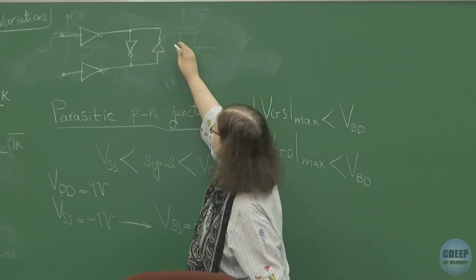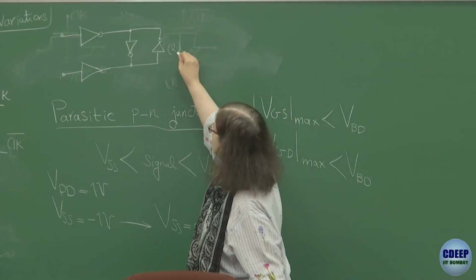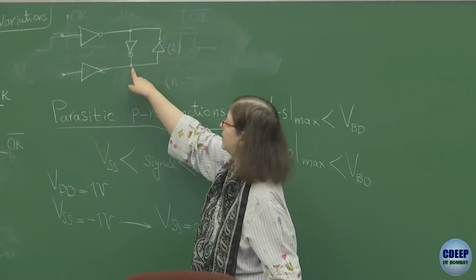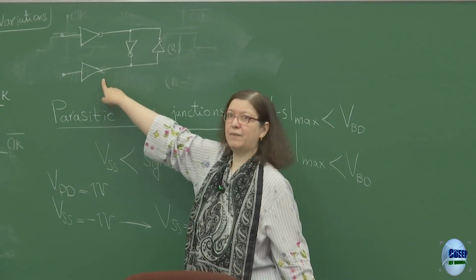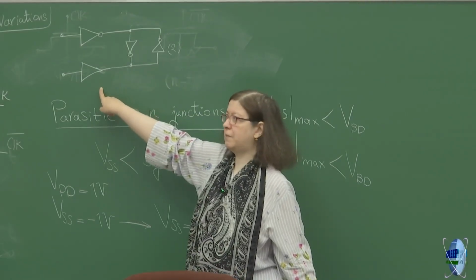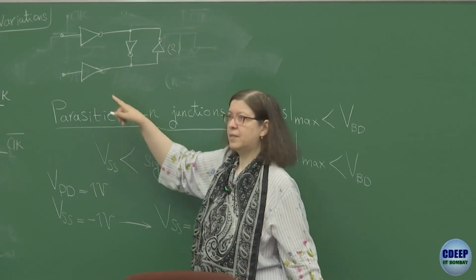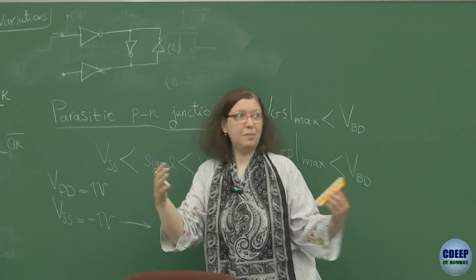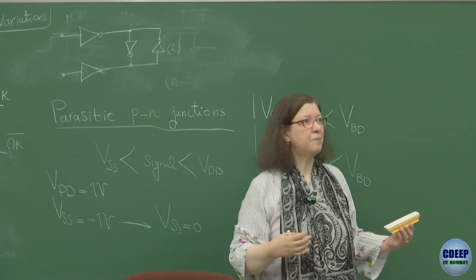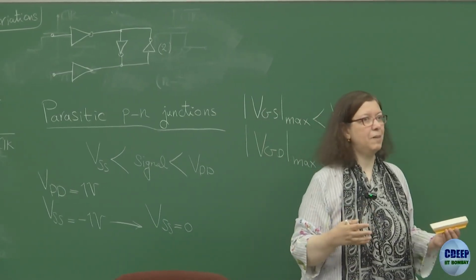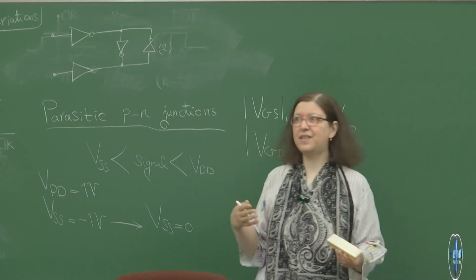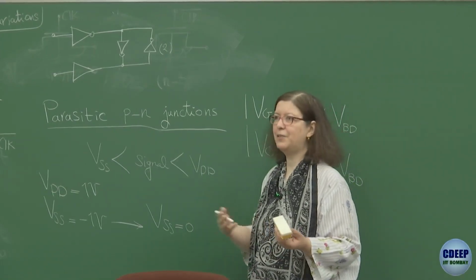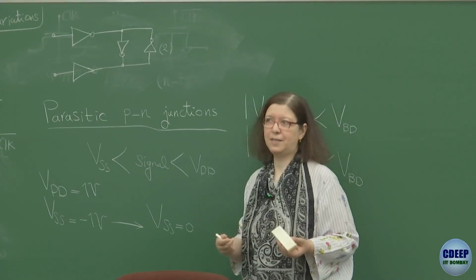It's like this inverter 2 is fighting with the variation at this node because it is already taking input from the slower inverter or slower buffer, or this could be 2 inverters. So because of this continuous fighting, you are coupling them to each other. Therefore, the fastest element needs to wait for the weakest element. So eventually, they will reach a kind of synchronized speed.